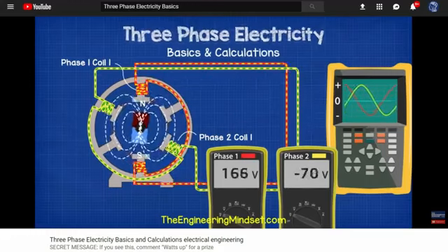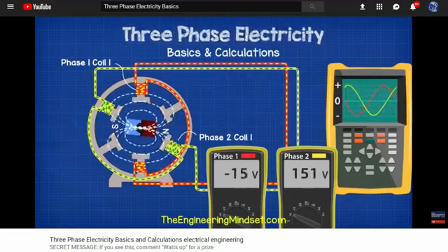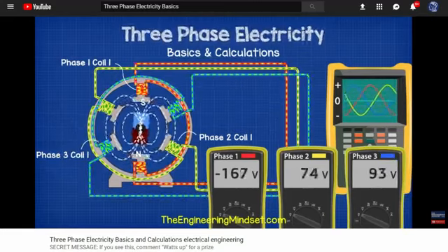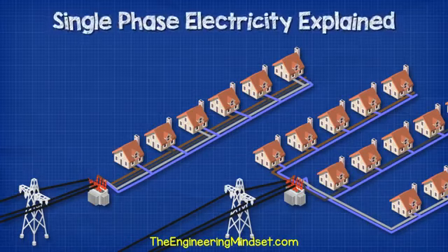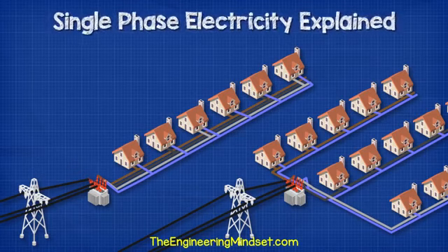We've also covered how 3-phase electricity works in a previous video, do check that out, links in the video description below. Now, each house in a street might be alternately connected to a different phase, or different streets might be connected to different phases. This is just to try and balance the demand on the transformer.